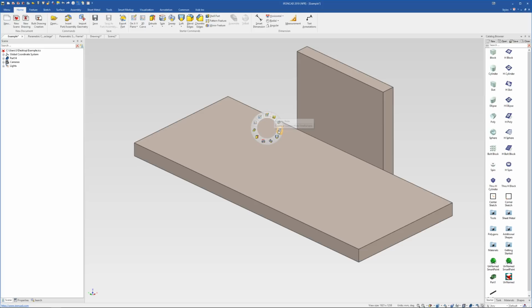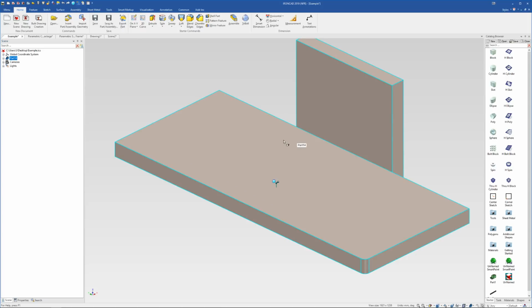If we know how to customize this, we can, for example, just select down to an edge like this, activate it, do a blend, and it's just going to drill through and do a blend for us. So it can be quite useful, but you just need to know how to customize it.